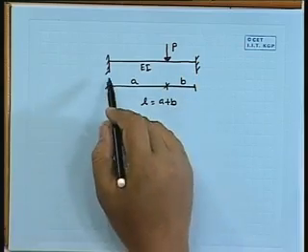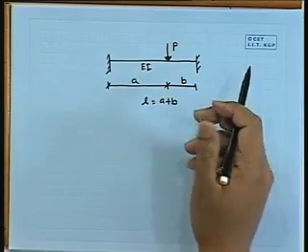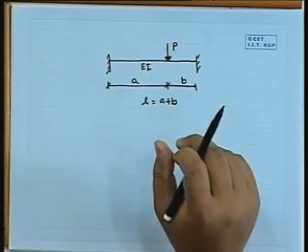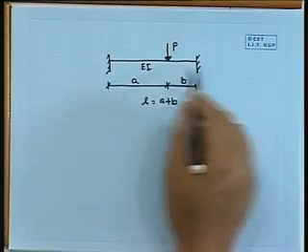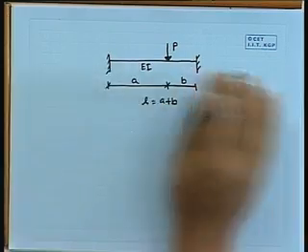No, it will not stretch. So the right end is fixed along with the left end. If we remove the right end, it will be a normal determinate cantilever beam. So if you remove the right end, how many reactions will you eliminate, or have to take in the form of some reactive force? First of all, it will give a vertical reaction force, plus there will be a rotational part. Now the horizontal part we are not considering, because there is no horizontal force, and the horizontal force here and here will cancel. Okay.